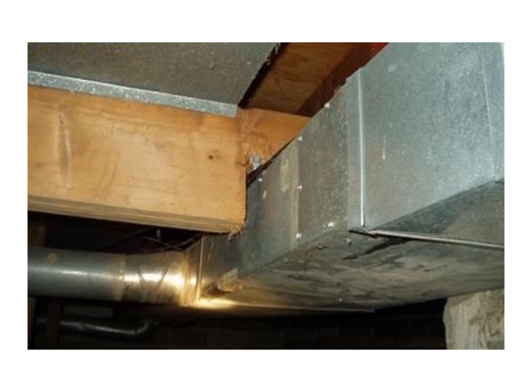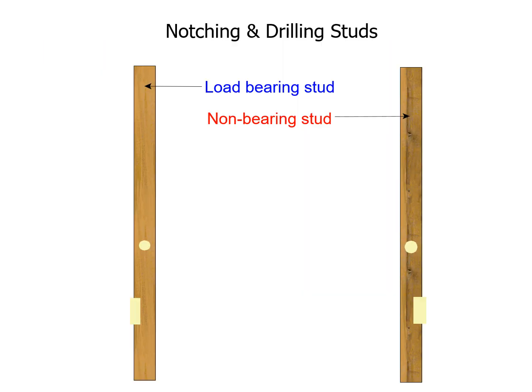There's one AC cut. Now this is a triple joist, and someone notched half of it out. And to me, it looks like that's the AC contractor. And again, they just don't care. He got his job done. It's as bad as us telling a plumber, hey, put a 4-inch pipe in a 3.5-inch wall. They'll do it. It's a little bold, but acceptable methods.